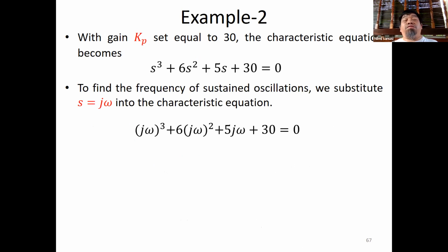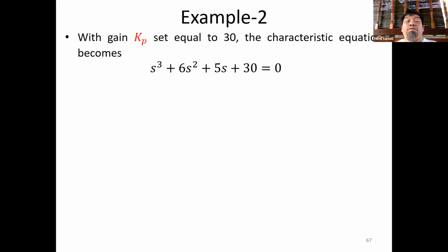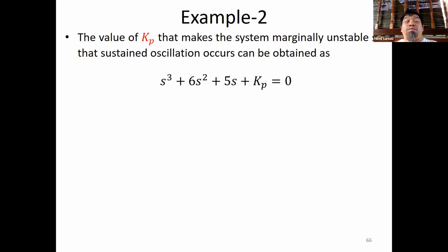You can use MATLAB also to do this. For the root criterion, in MATLAB, the old version has it, the new one I'm not sure. We can take a look. Okay, if using calculation, put in your gain Kp here. Looking here, this is your transfer function. If you have your Kp, then you get your closed loop: Kp over (S plus 1)(S plus 5) plus Kp.